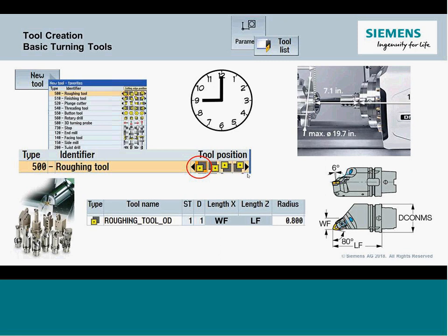And the system is going to manage that distance that I mentioned earlier, which is the center of the rotary to the line or face of my spindle. That's happening in the background. And that value is critical, because if you imagine that B-axis swinging around, if I don't know that distance, I never come up with a calculation of where that tool is now that I kicked it down to 45 degrees. So as you start to do some tool setup, you're going to see the offset values are going to be that distance. You could obviously have set these tool offsets up externally and just plug the numbers directly in.